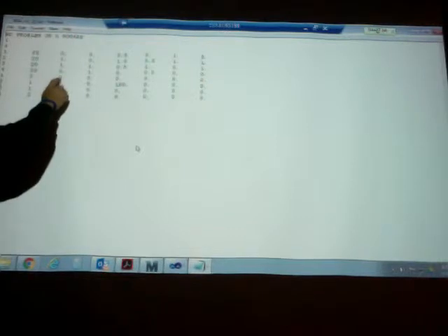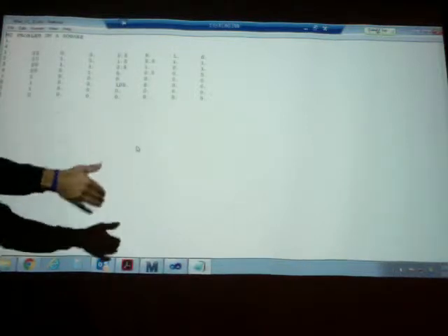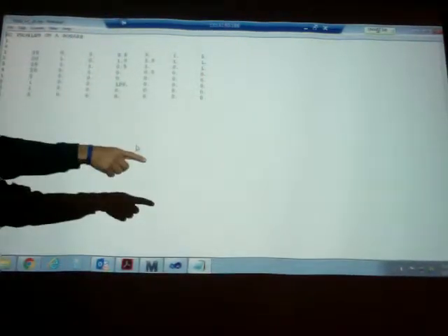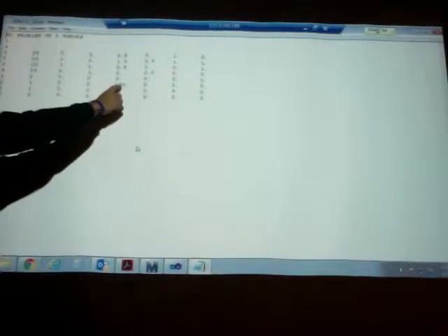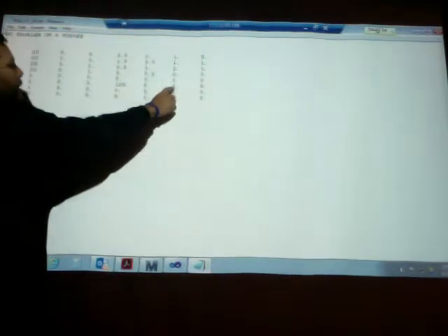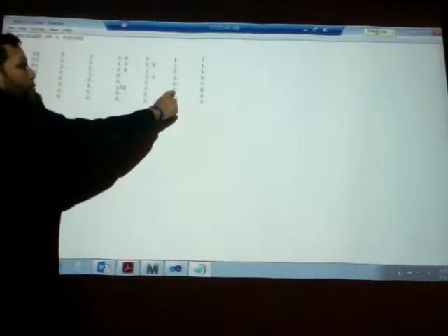Then I'm imposing the boundary conditions for the 4 segments. The first segment is insulated, type 2, flux equal to 0. The second segment on the right-hand side is type 1: temperature at the bottom right corner is 0, at the center of the right wall is 100, and at the top right corner is 0.